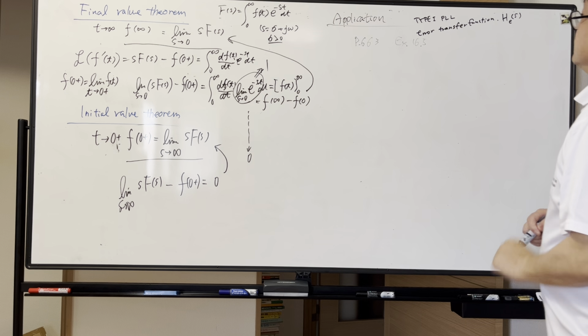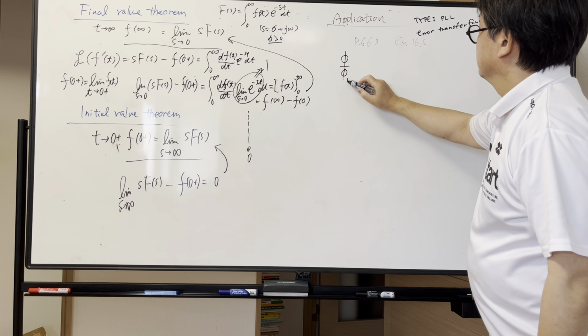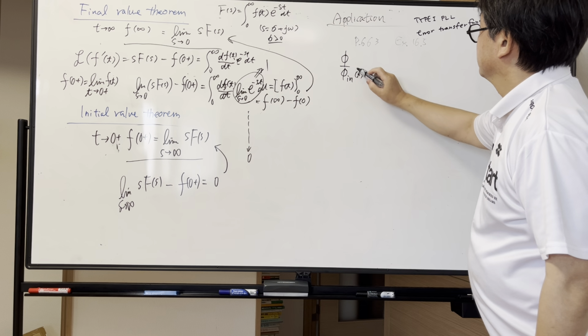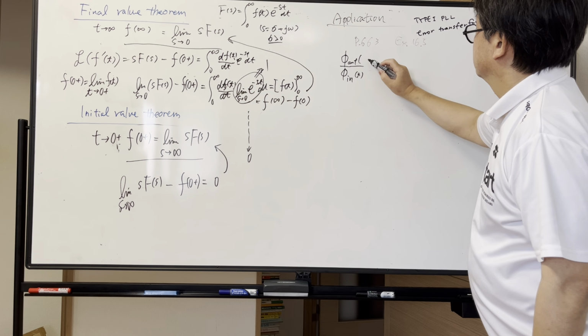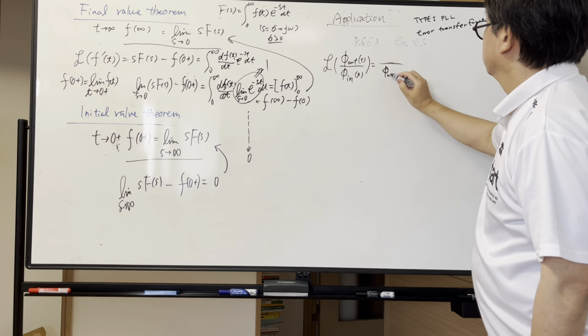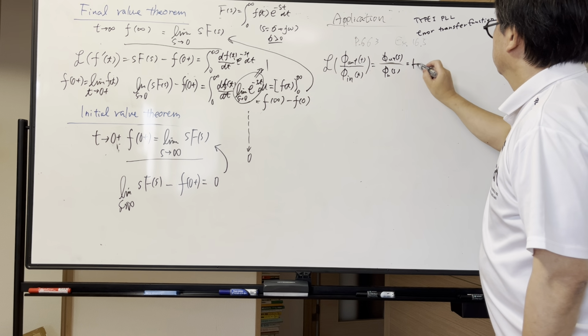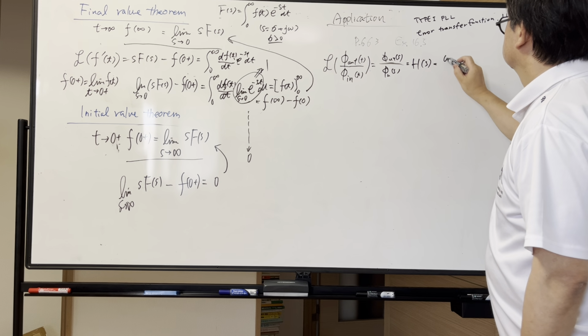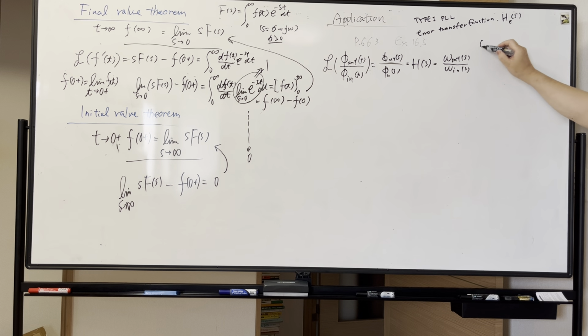The error transfer function is about the phase, phi in to phi out: phi in of s, phi out of s, and H of s is actually omega out of s divided by omega in of s, where omega equals d phi dt, and d dt is a linear operator.